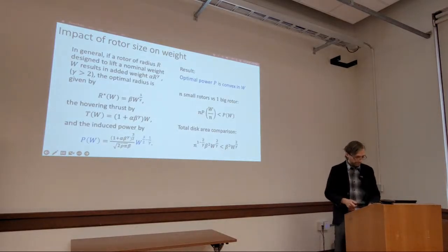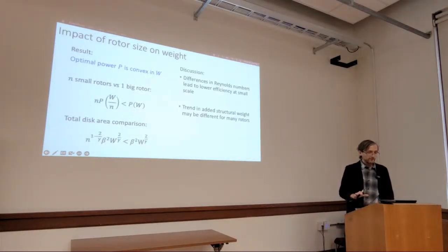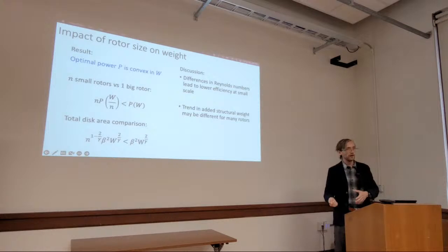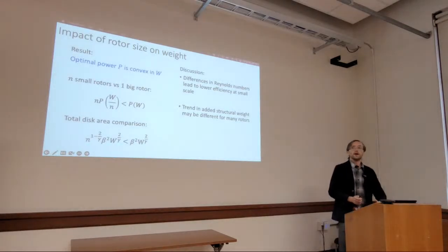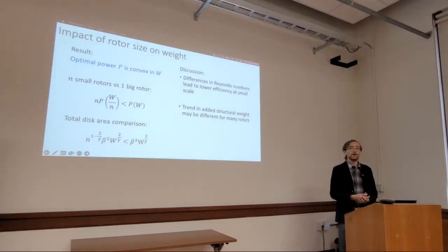And so, why is it not always true? What are the reasons for it not to be always true? If we look at the Reynolds number, which is lower for small rotors, there will be more viscous effects and more losses at the rotor for small rotors, okay? So this conclusion that I got from momentum theory, by considering the added weight that comes with a larger rotor, will not be true for every possible rotor size.